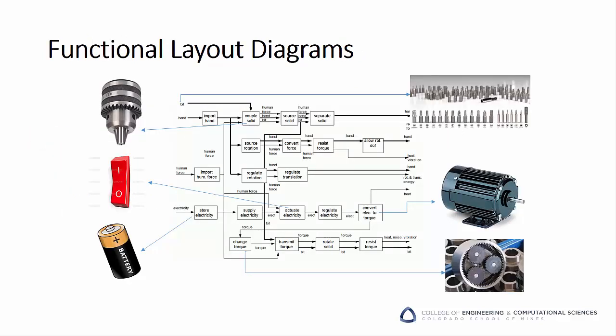Let's look at a textbook example of embodiment design. Literally, this came from a textbook. This is the functional diagram for a proposed electric screwdriver. You can take your functional definition of the product, which hopefully you've captured and which is covered in another module, and start exploring how hardware could be assigned to accomplish the different functions. So, store electricity becomes a debate about types of batteries to be used, and looking at the couple solid function leads to a comparison of different alternative chuck systems.